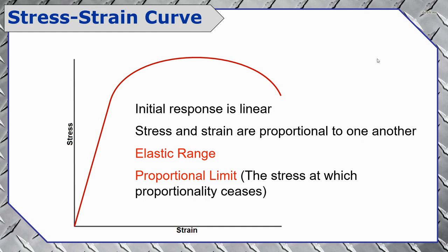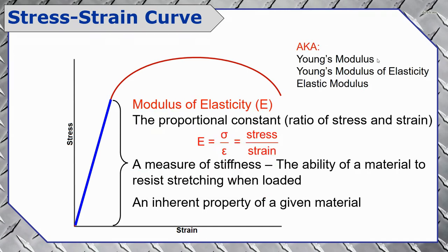That means if the force is removed, the strain will recover and the material will stretch back to its original size without damage. As more force is applied, the relationship will continue this way in a linear fashion. This continues until we reach the point known as the proportional limit, where this elastic relationship between stress and strain ends and we start to see what is known as plastic deformation. So this is the first region of the curve worth examining.